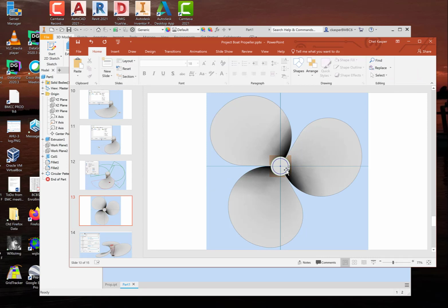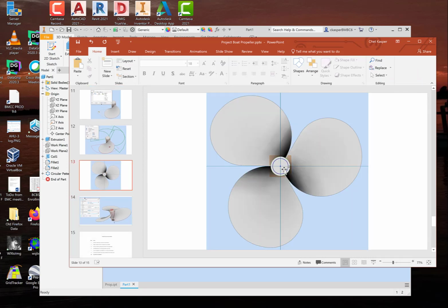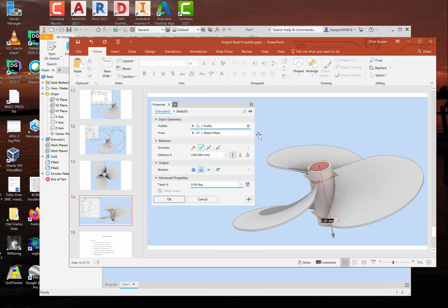So we've done that. What we start out with the extrude command is if you draw a circle on top of that cylinder, and once you have that circle there, you can then extrude that circle downwards through the solid, and the secret is right here, this thing right here. That is a remove material option. Usually it's this one, which is to add material. This is the one you use to remove material.